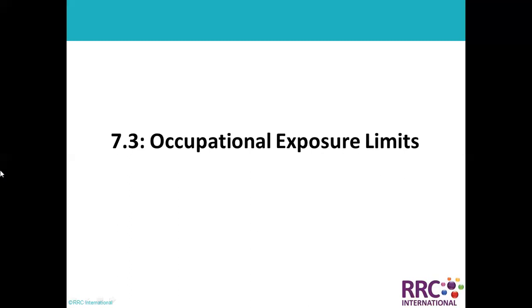Yes, absolutely. LEL basically is a cumulative rating of all the available ingredients in the air, mostly in the shape of gases, and it will give you the LEL reading. Now, my question is, if you are doing hot work like grinding, cutting, abrasive blasting, or any process which can create an ignition source, what should be the LEL in the confined space? Okay, let's make this the second question: LEL.